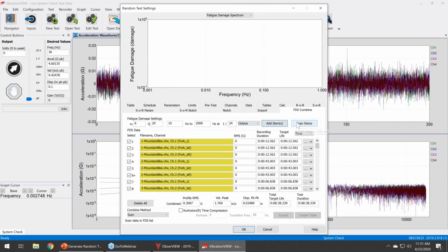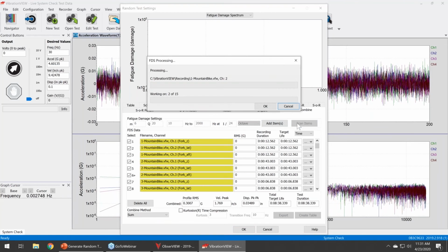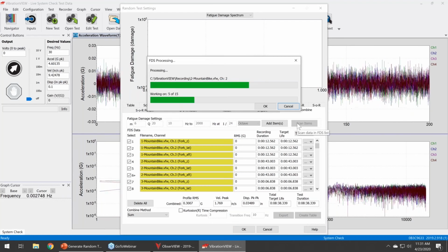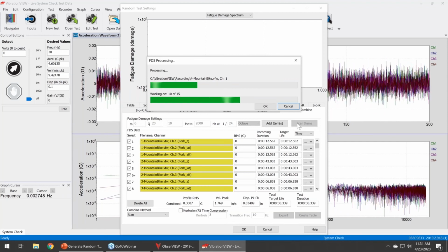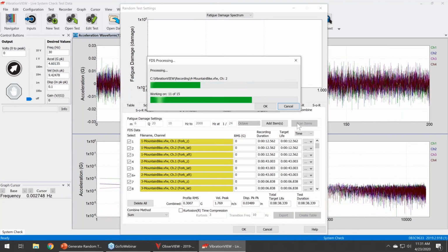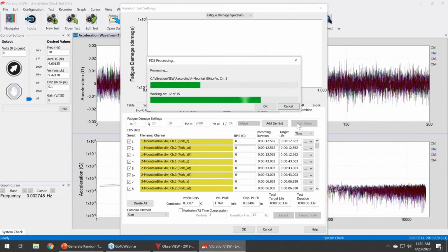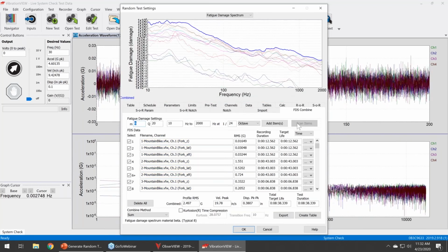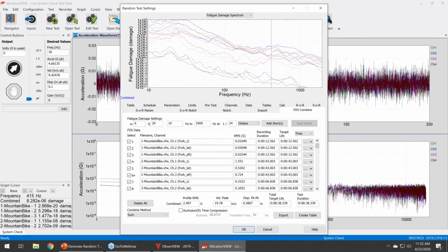We're going to click Scan Items. So this Scan Items now in Vibration View is going through that FDS process where we are converting that waveform into velocity. We are passing it through that series of single degree of freedom oscillators. For each narrow band or single frequency waveform, we are doing our rainflow analysis and cycle counting to generate the number of peaks that occur at a particular amplitude for a particular frequency, then running that through our damage calculation. And the end result is this information at the top of my screen.